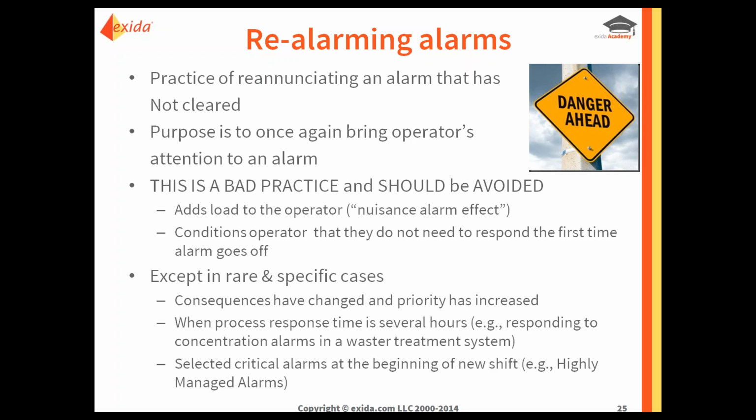And then for a very select group of critical alarms, you may want to re-enunciate those alarms at the beginning of a shift. So when a new operator comes on, for example, any highly managed alarms, or safety critical or safety related alarms, you may want to re-enunciate them so that they are back at the top of the screen. The operator has to acknowledge them. They need to respond. They need to investigate. It's right in the front of their mind, which is very different from if the alarm is active and buried on the screen somewhere. So that's the other scenario where it may be useful to use this technique.